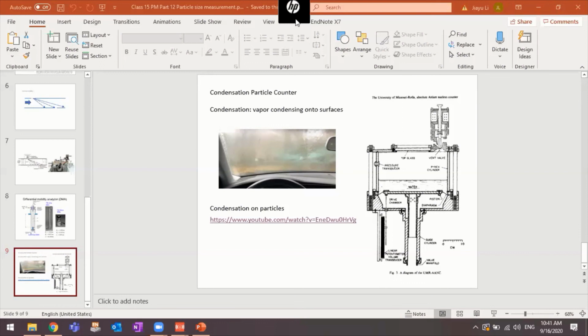But in terms of mathematics, I would say if it's 100 times larger, that's much larger. If it's 1% or lower, that's much smaller. You can use this as a guideline to decide on the Cunningham correction factor. If the particle is, let's say, 10 micron, then it's much larger than the mean free path, so we don't need to worry about the Cunningham correction factor. We can just regard that as 1, right?